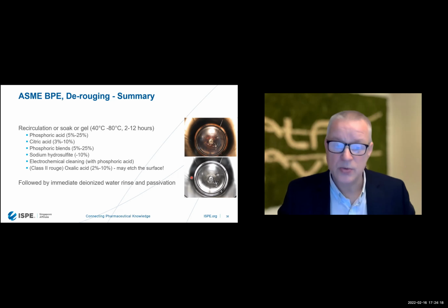So no strict guidance. And the follow-up to that question is about the use of online rouge monitoring instruments now available on the market. What do you think about their usage? Well, I think they are good. Let me see, we have the measure rouge here. What could be interesting is the electrochemical impedance spectrometer, because it's non-invasive and it measures the actual source of the rouging.